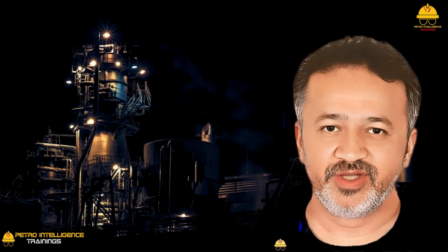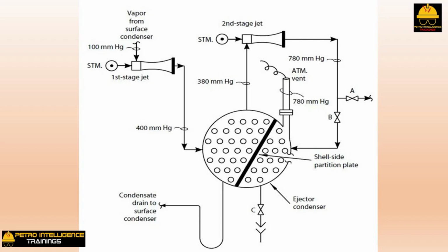The solution to this problem was not to repair the defective ejector condenser. This had been done before, but without preventing a repeat failure. As I've explained in lecture, the final or second stage condenser serves no function. It's a design error. So, in this case, as shown in the picture, valves B and C were shut and the local atmospheric vent valve A was opened.